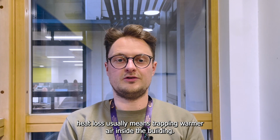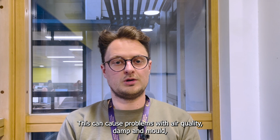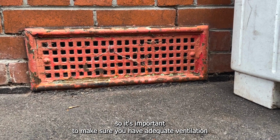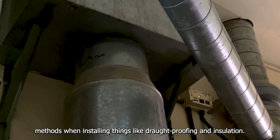Reducing a building's heat loss usually means trapping warmer air inside the building. This can cause problems with air quality, damp and mould. So it's important to make sure you have adequate ventilation methods when installing things like draught-proofing and insulation.